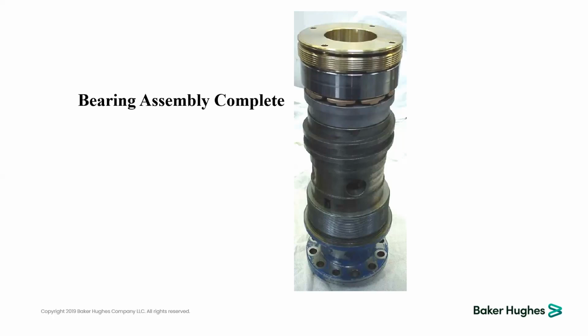In the bearing assembly shown in that photo, this is the bottom section of the seal section, the bottom chamber. The bottom chamber is acting on the thrust function of the ESP seal, which is the absorption of the thrust created by the pump, impeller, diffuser, and the shaft of the entire ESP equipment.